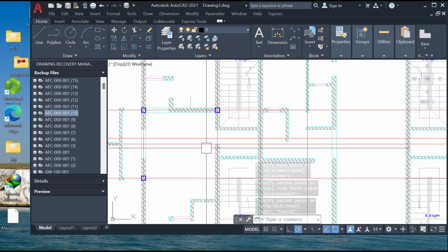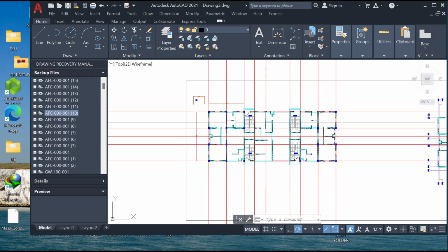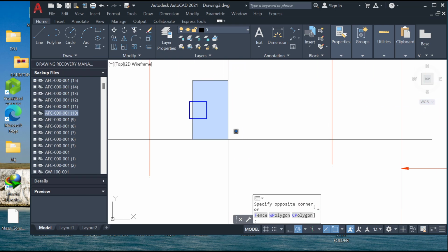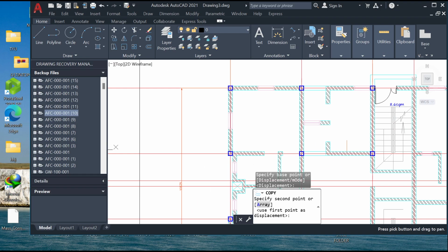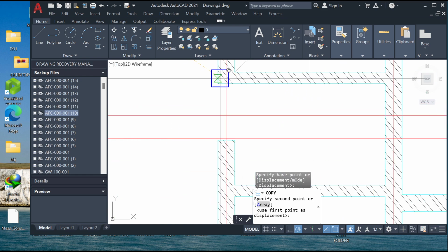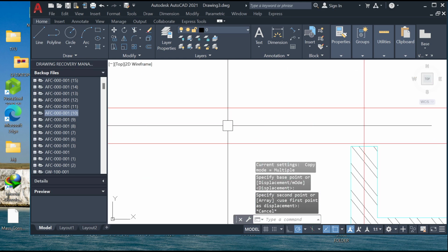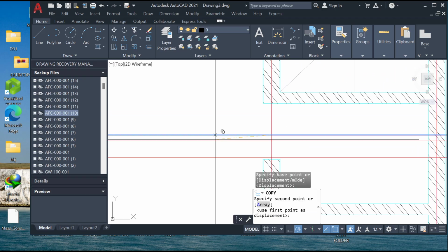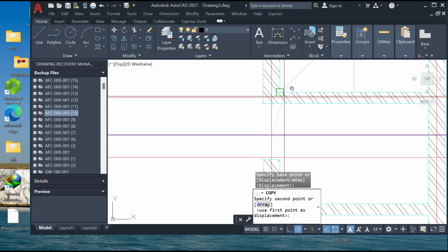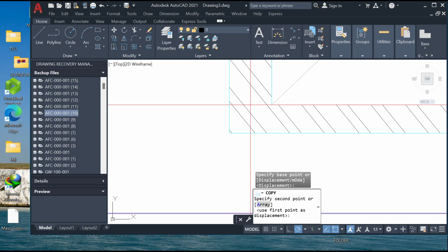So what I've just done tells me that I cannot put my column here. This is where I need to put my column. I need to put it at the landing so it can be able to carry the landing. So let's put one here at the landing. Okay, you see that we don't have a grid line here. Like I said, the grid lines are not sacrosanct. Any we don't need, we are going to remove, and any that we did not put, we are going to create. So we'll put one here.